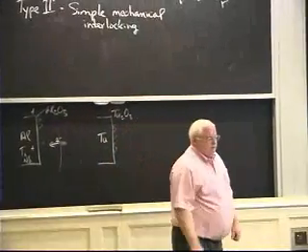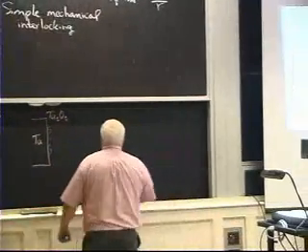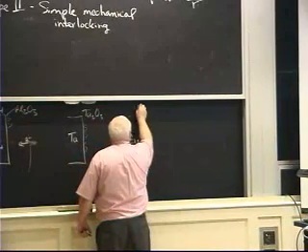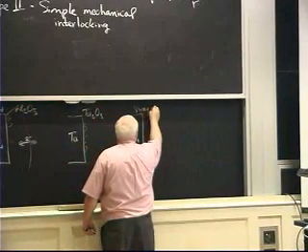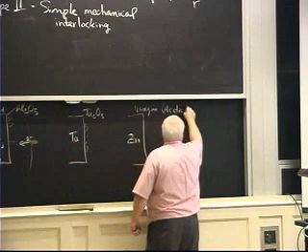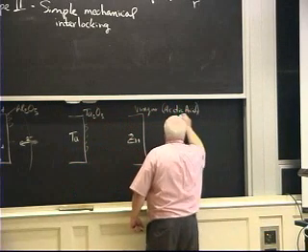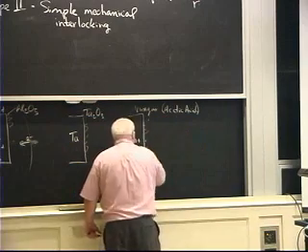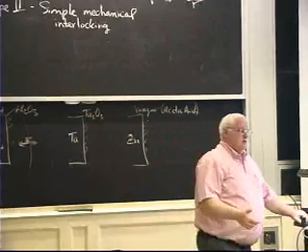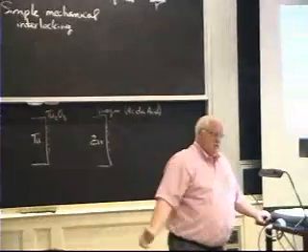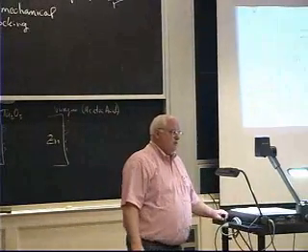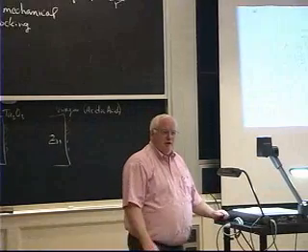So for zinc, if you have a zinc surface, basically you use vinegar, or we use acetic acid because I can get it by the gallon here. Okay, and you grow a zinc acetate film on the surface, a very porous layer on the surface. And so the first week we had the Scouts out there scraping the paint off, which you guys are familiar with having to do that, right?